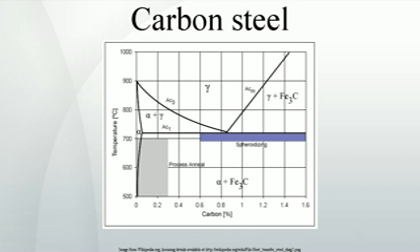Quench and tempering. This is the most common heat treatment encountered, because the final properties can be precisely determined by the temperature and time of the tempering. Tempering involves reheating quenched steel to a temperature below the eutectoid temperature then cooling. The elevated temperature allows very small amounts of spheroidite to form, which restores ductility, but reduces hardness. Actual temperatures and times are carefully chosen for each composition.